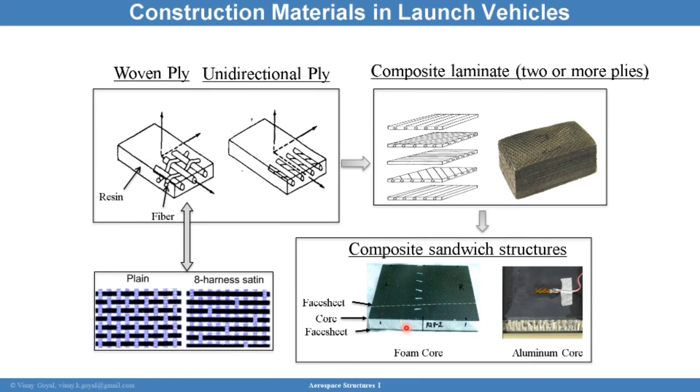If you recall from mechanics of materials, the bending stiffness is EI, where E is the modulus of the material and I is the second moment of inertia. For a rectangular cross section, I is 1/12 b h cubed, where h is the thickness.